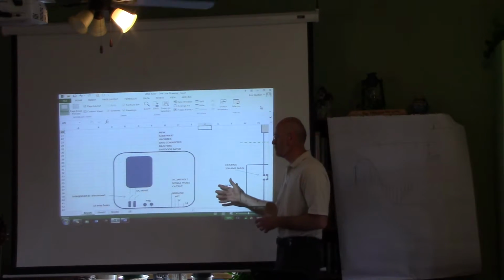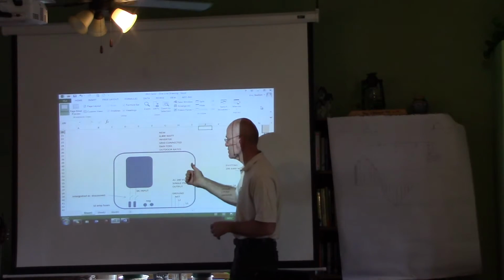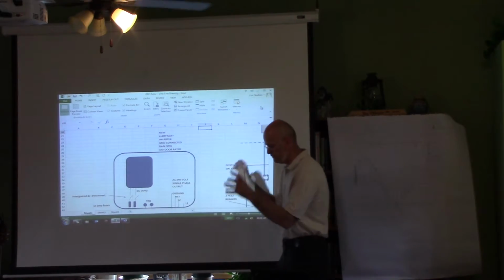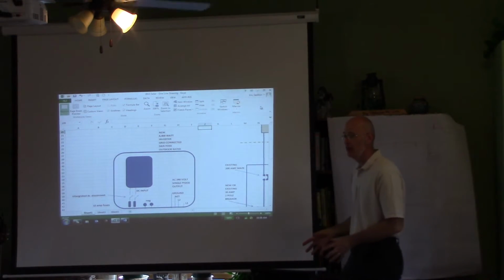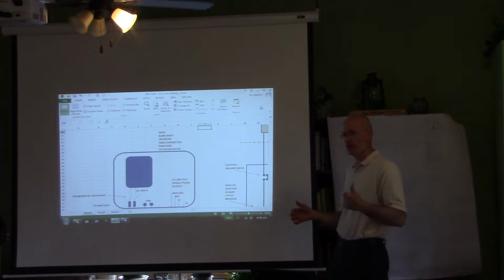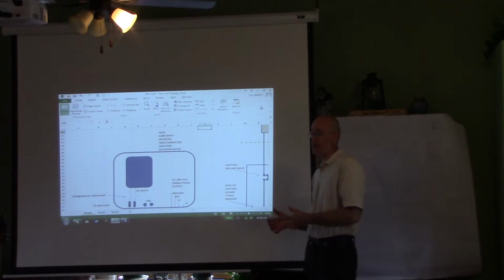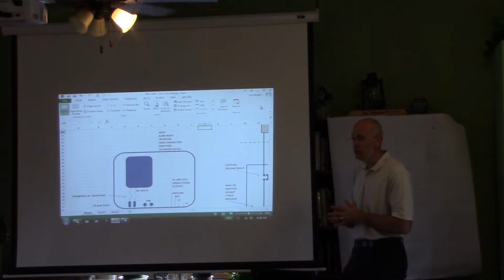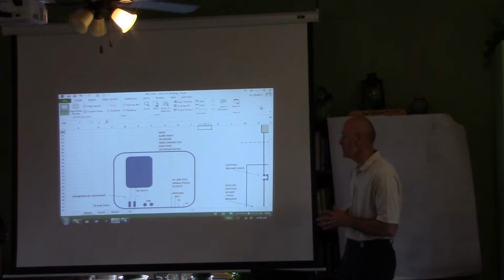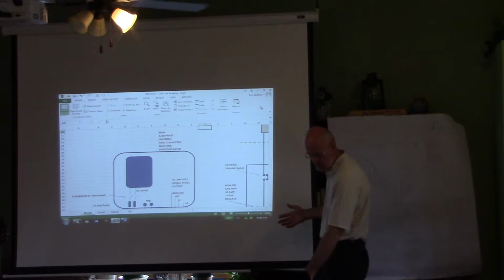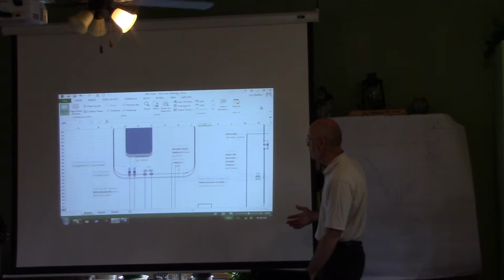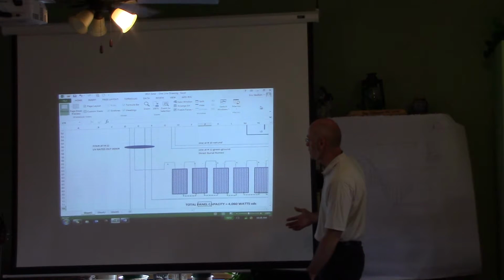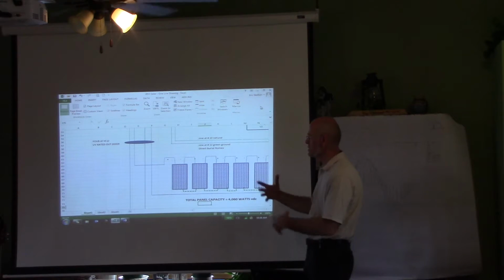In this particular inverter, it's going to heat sink it. It's going to dissipate it in the metal fins that the chassis is built on. It'll take that excess energy and dump it to heat and get rid of it. It's not a good design. It's not the right way to do it. It's not efficient because you spent money on panels that you didn't need. Okay? And then the heat's getting dissipated.